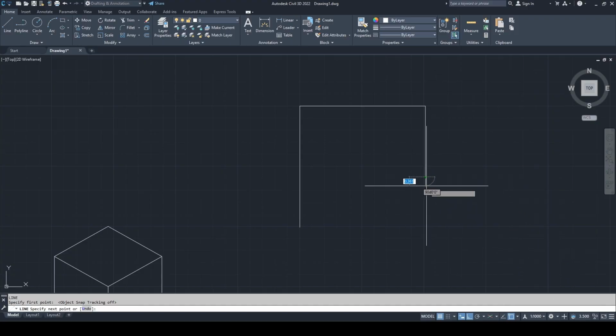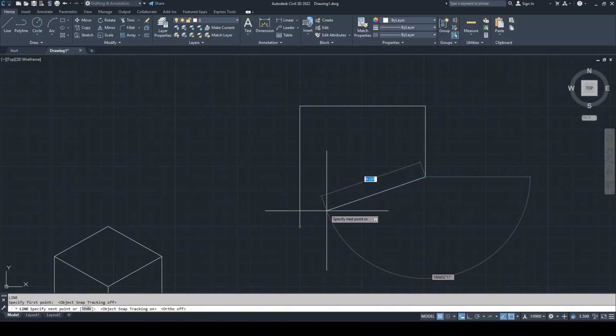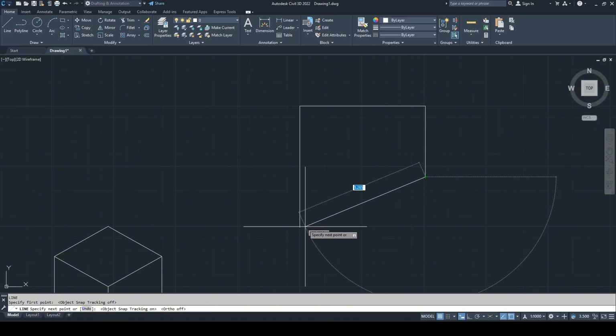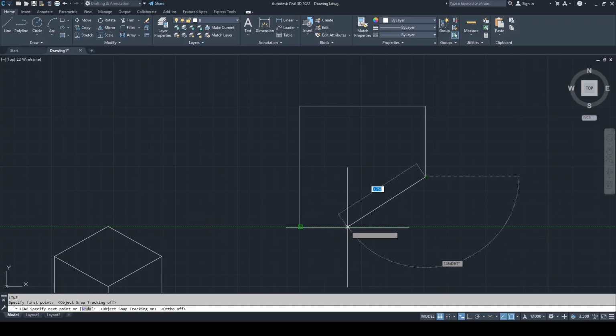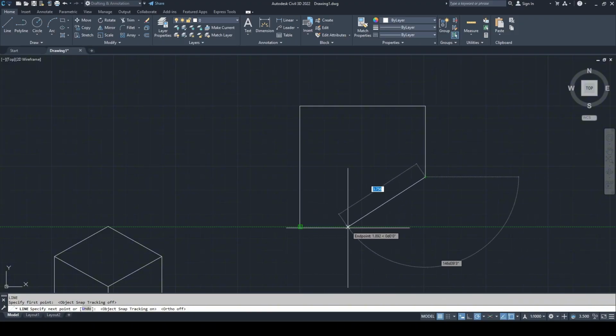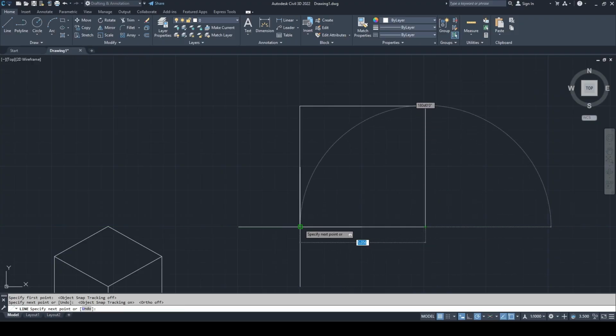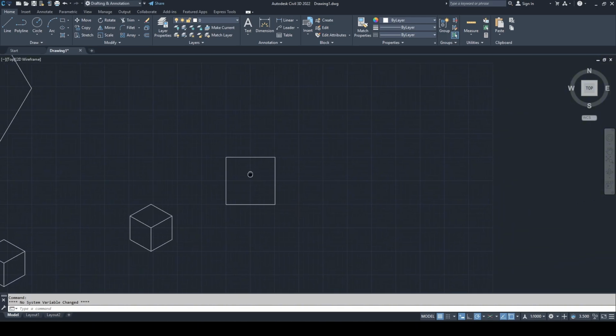And now you can see I am making another line, but I am still not sure whether I can place this line so it will be parallel to this line. So for that, let me turn this on. Let me turn the ortho off also. Let me go to this point, and it will give me the tracking line. Let me change the angle also, for a reference line for this object to be placed perpendicularly. So now I can easily close this box. Give you another example.